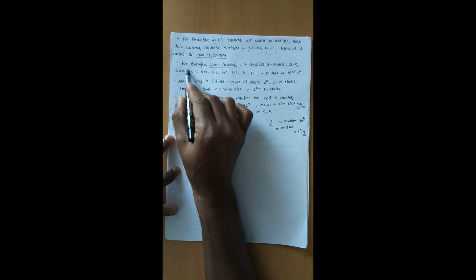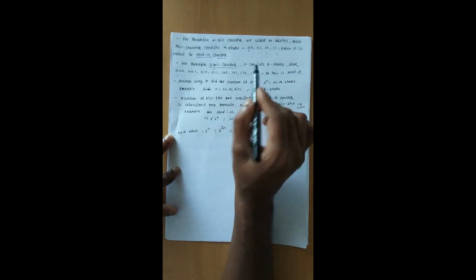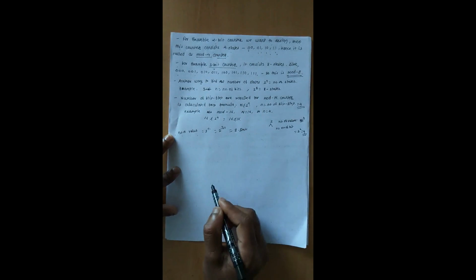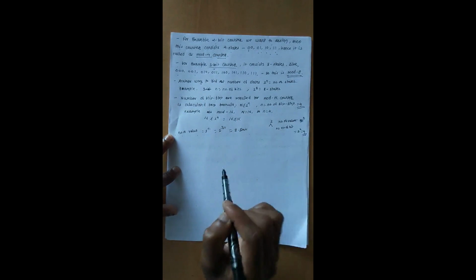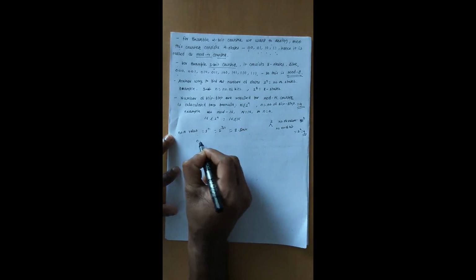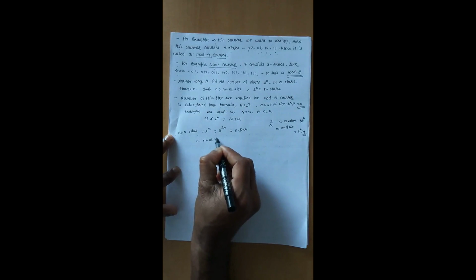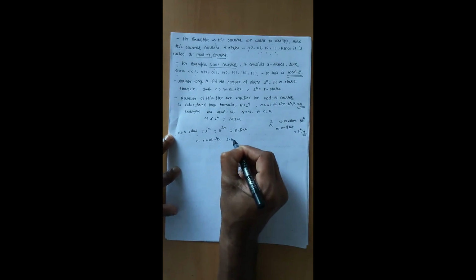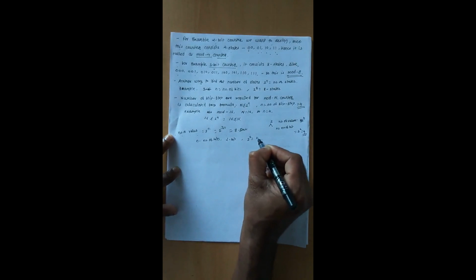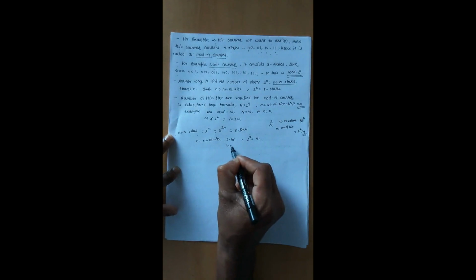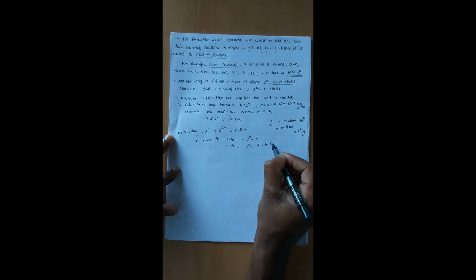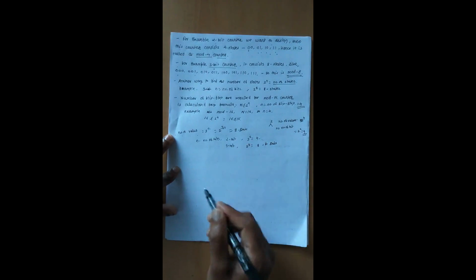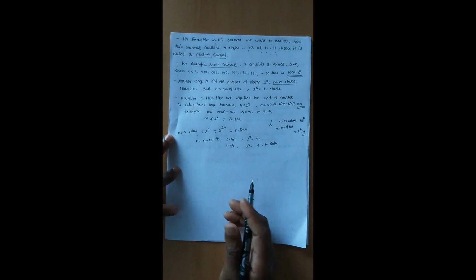Hence this counter passes through 8 different states, so it is called a modulus of 8 counter. Another way to find the number of states is 2 raised to n. What is n? Number of bits. Suppose this is a 2-bit counter, so it will be 2 raised to 2, which becomes 4. This produces 4 different states. Suppose this is a 3-bit counter, it will produce 2 raised to 3, 8 different states. This is another approach in which we can easily find the number of states.